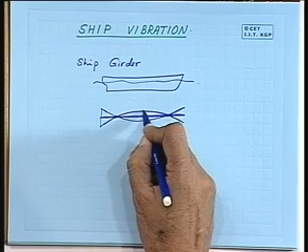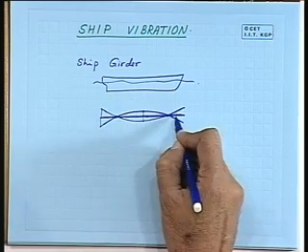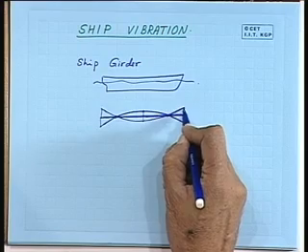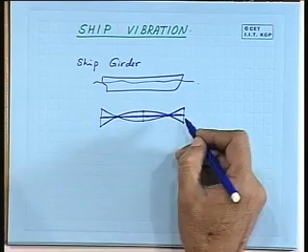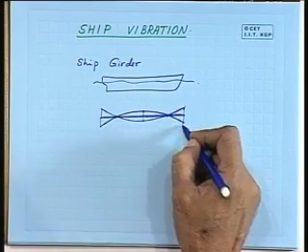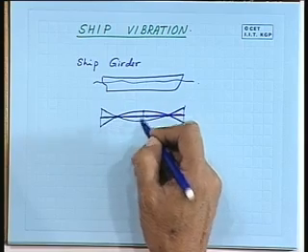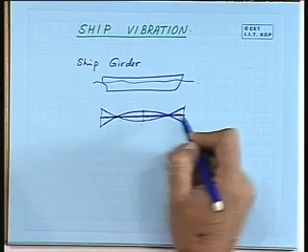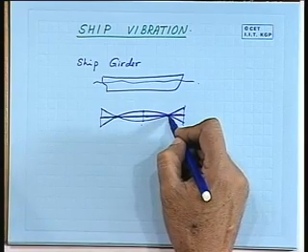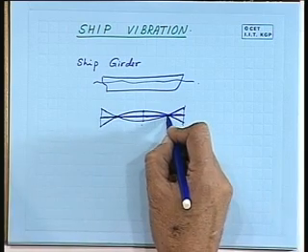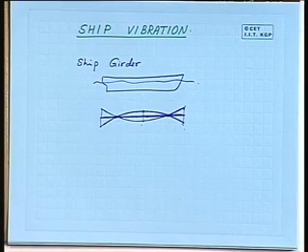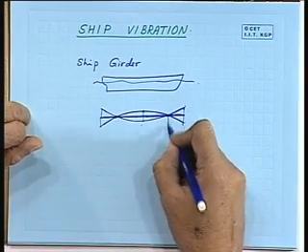This point also goes up here, down here. This also goes up here, down here. So, this particular point has got this much of displacement. This point has got this much of displacement, but this point does not have any displacement. So, the points on a particular structure which do not undergo any displacement, or the points of zero displacement are known as nodes.